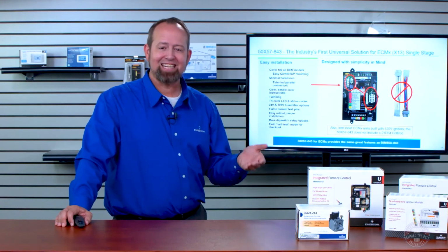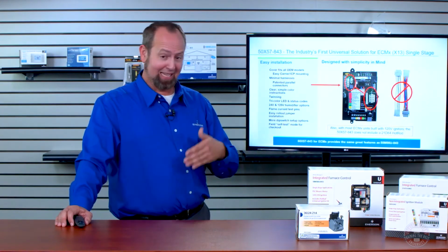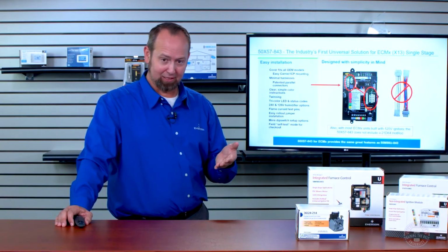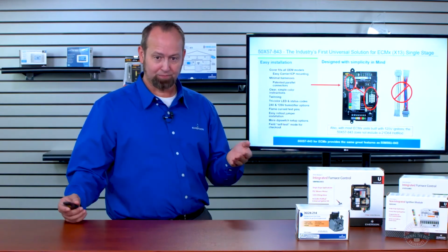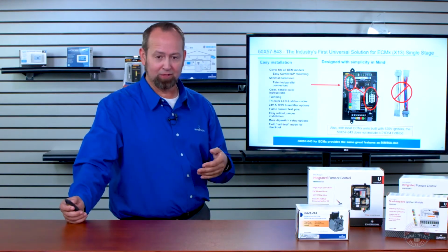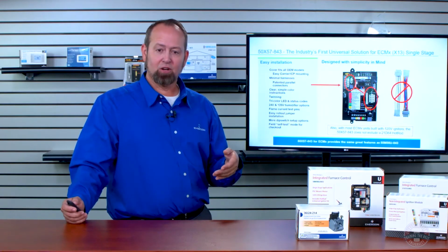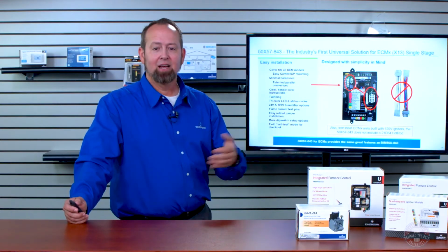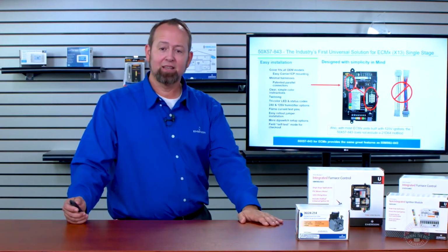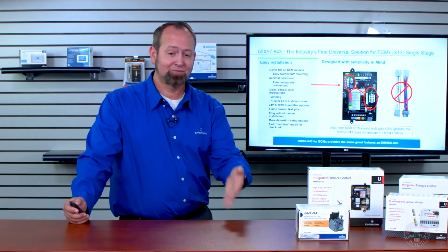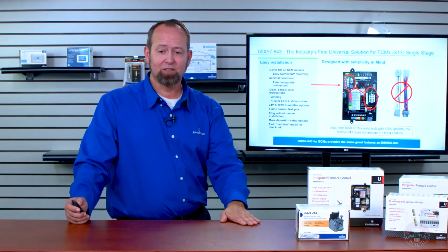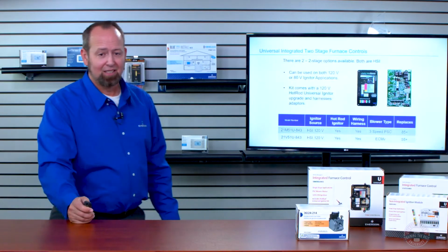So you're not needing to replace that igniter in this application. It's already 120 volts. And we were able to lower the cost on the kit by not having that extra component in there with it, because your existing one would function fine as it is.